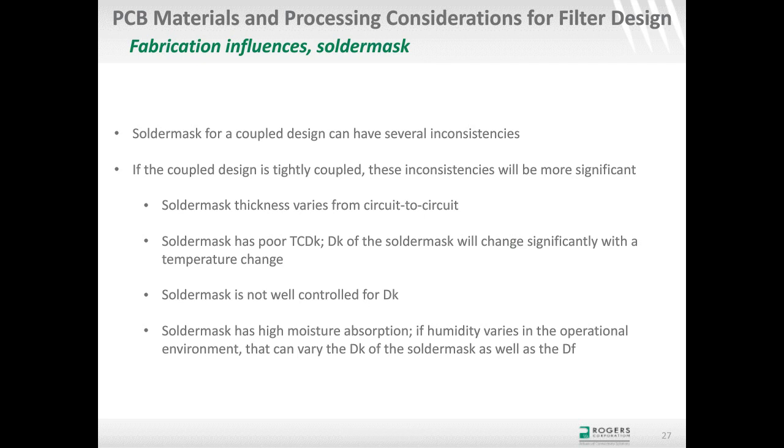The dielectric constant of solder mask does have some normal variation, but it's not really controlled, so that's another possible variable. And then finally, moisture absorption can be a pretty big concern with applications that are out in the field, where the circuit is being exposed to different levels of humidity. A very humid day one day, dry another day, could make a difference in the moisture absorption of the solder mask, where it would absorb more or less moisture. And that difference in moisture will make a difference in the phase response of the circuit and the insertion loss as well.